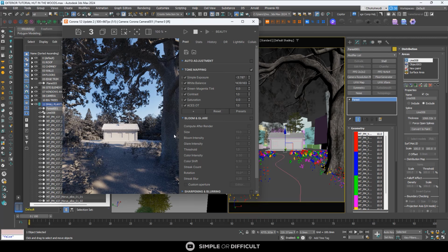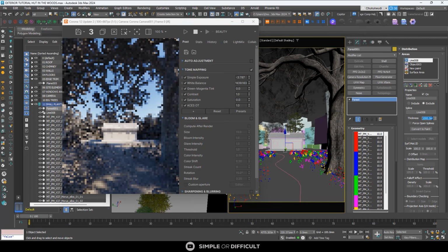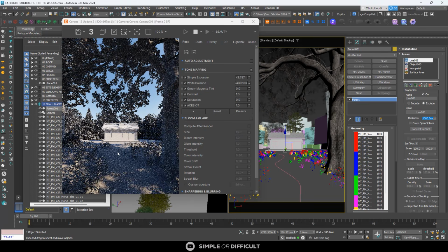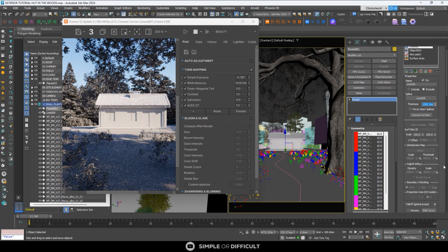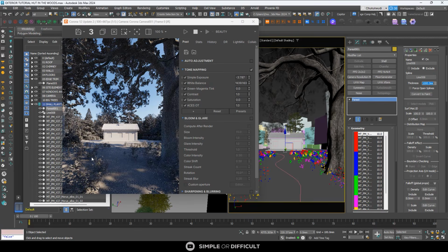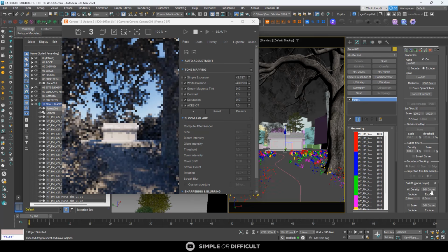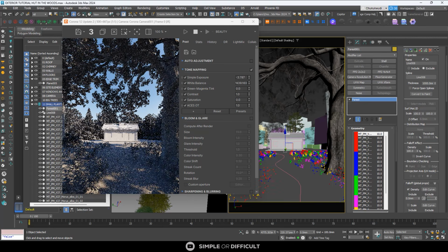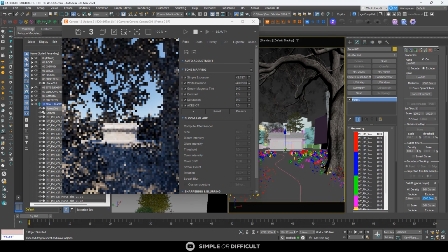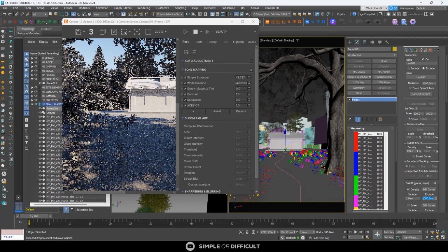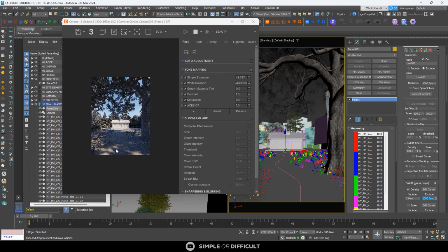As you can see, that's the driveway right here. So let me just make this 1,000, just 1,000. Now I want to add fall off so that as the plants get closer to the road, they are getting smaller and tinier, for realism. So I'm going to put density and type another 1,000 in here. You see, this area now will be chopped off a little bit.